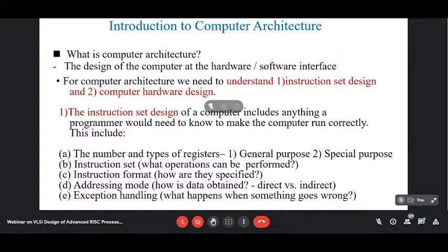It has a number of interrupts, like hardware interrupts such as INTR, TRAP, RST 5.5, RST 6.5. They are the interrupt lines, like if a signal comes over there, how the CPU will react to it. So in fact, when you design the instruction set, all these things have to be kept in mind. We'll discuss all these things when we go for the detailed architecture.